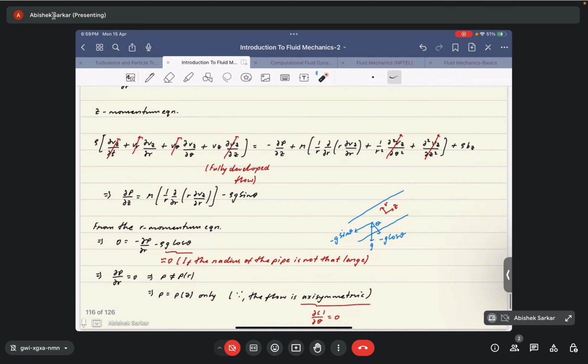Okay, so from the r momentum equation we have that 0 is equal to minus dou p by dou r minus rho g cos theta. Now if the pipe is really thin, or the radius of the pipe is much smaller than the length of the pipe, then this body force component can ideally be neglected. Because the variation of pressure along this length would be almost negligible compared to the variation of pressure along this direction because of the length of the pipe. Because of the pressure gradient that exists between the two ends of the pipe that causes the flow.